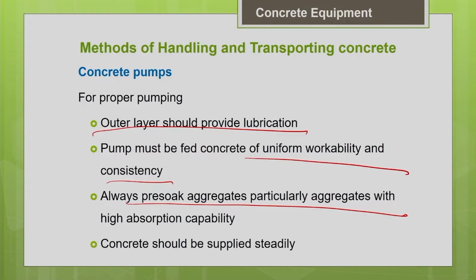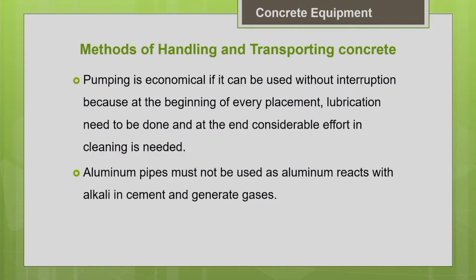Then another important thing is pumping is the best option when the concrete is needed on a steady basis. You need a steady supply of concrete, then pumping is the best option. As I told you, it involves a lot of preparation procedures like lubrication, and after pumping you have to do the cleaning. All this involves a lot of effort. So, for a steady supply of concrete this is the best choice, but for intermittent placing of concrete pumping is not the right choice. Pumping is economical if it can be used without interruption.